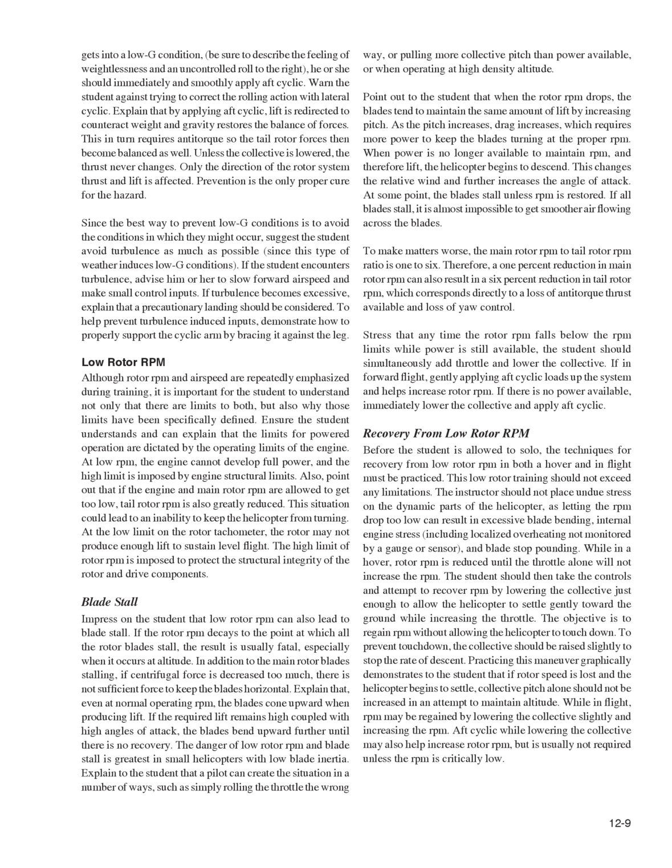While in a hover, rotor RPM is reduced until the throttle alone will not increase the RPM. The student should then take the controls and attempt to recover RPM by lowering the collective just enough to allow the helicopter to settle gently toward the ground while increasing the throttle. The objective is to regain RPM without allowing the helicopter to touch down.